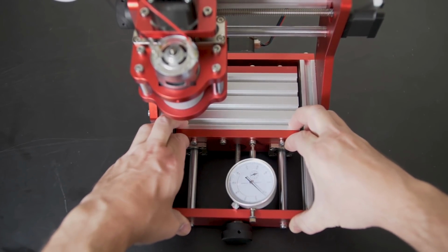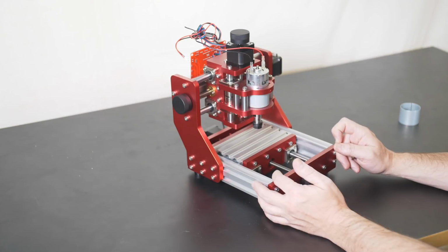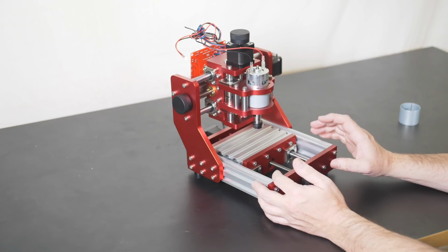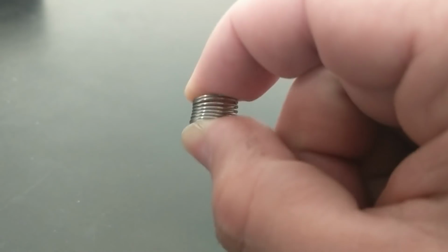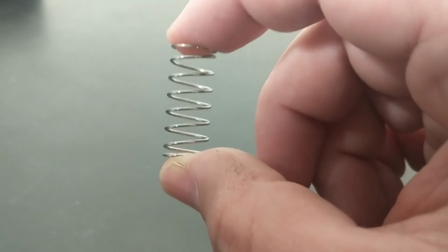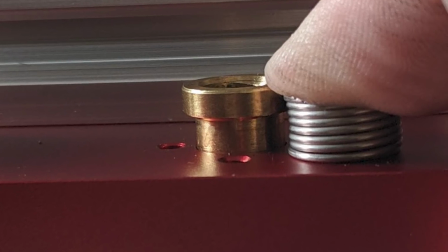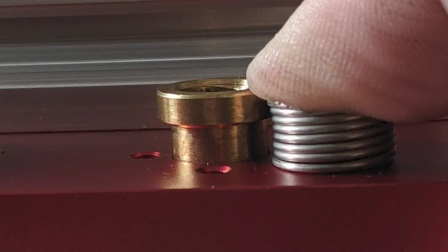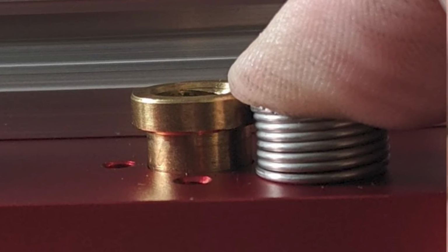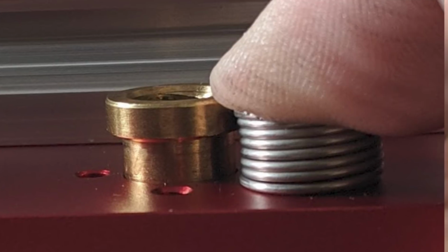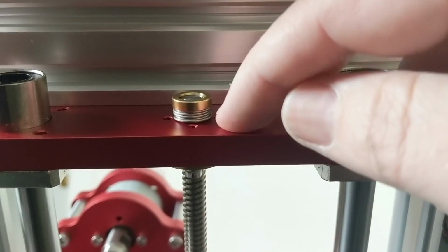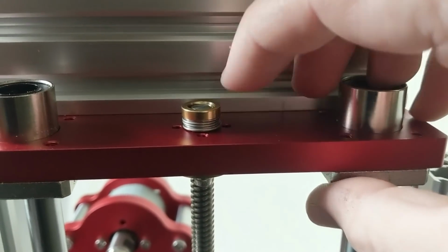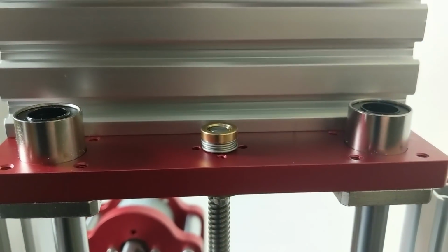Now that bed is moving the thickness of a piece of paper, and that's pretty substantial, and it's going to manifest in your final geometry when you're cutting things. So we definitely want to fix that, and here's how you do that. This is the spring that comes with the anti-backlash nut, and we need to shorten it so that it can work correctly. So take a look at this picture where I'm holding the spring compressed next to the anti-backlash nut fully installed. So you need to match that gap there underneath the shoulder of the nut. In this case, I need 5.5 turns. There we go. See how tight that is? We should have no more problems, at least not the normal operating forces of this small machine.